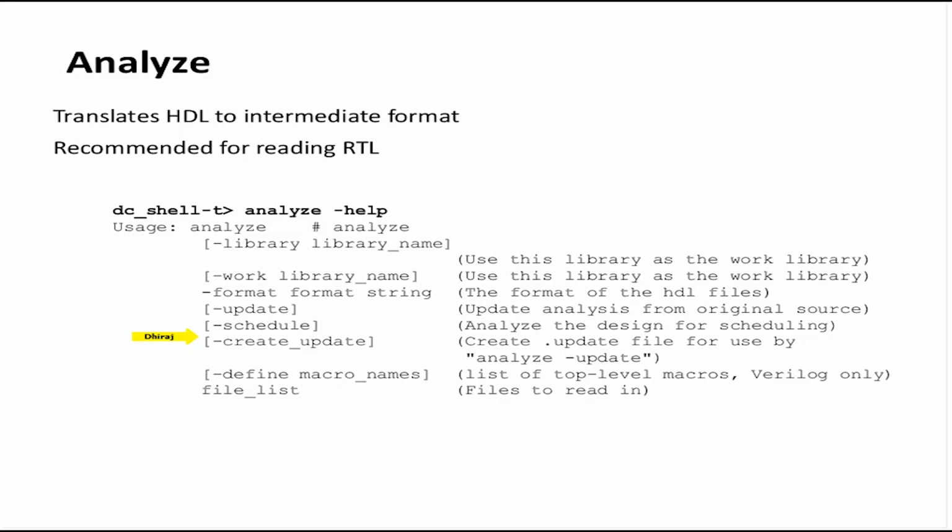So what analyze actually does is it enables you to define macros while reading a Verilog or VHDL file. Obviously, for VHDL, the macros are not supported there. So it analyzes simply, and it will also tell you what all syntax errors your RTL files contain. So once you pass analyze, it means that at least your code is syntactically correct. Then what follows is